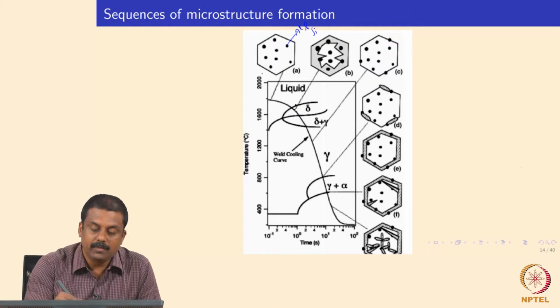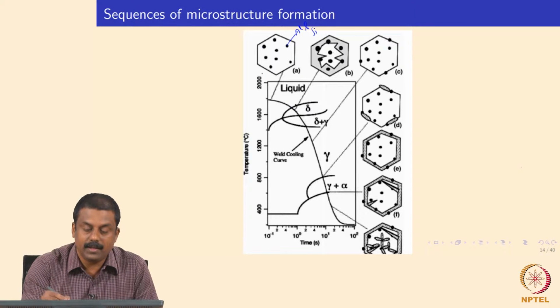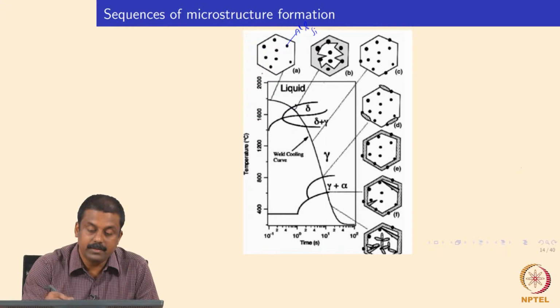Subsequently, when you cool down upon reaching the solidification start temperature, you will nucleate delta ferrite in steels, even in conventional advanced steels like DP and TRIP. You solidify first into delta ferrite, and subsequently the alloying elements either go to the liquid or partition towards delta ferrite, especially aluminum, while other elements try to partition towards the liquid.